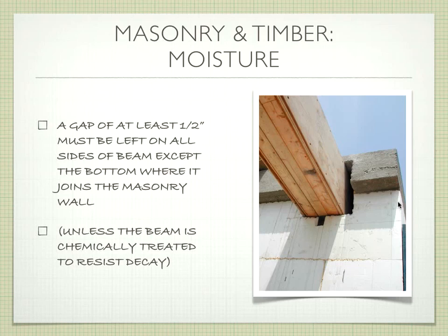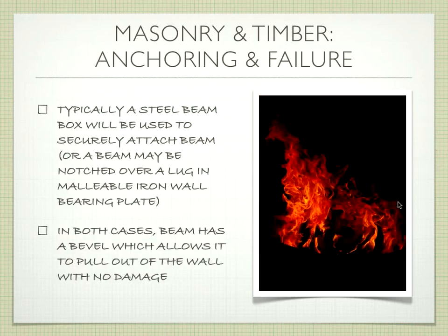Okay? If the beam is chemically treated, though, pressure treated, we talked about that last week, or 2 weeks ago, because of spring break, if it's pressure treated, then it's resistant to rot, so we don't have to worry about that gap. So this is if it's a non-pressure-treated piece of wood. So that's how we handle that. Okay?